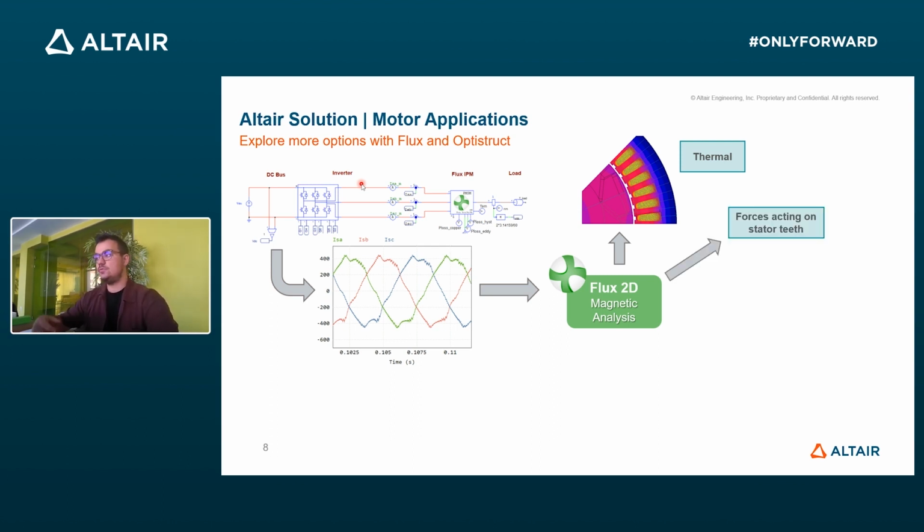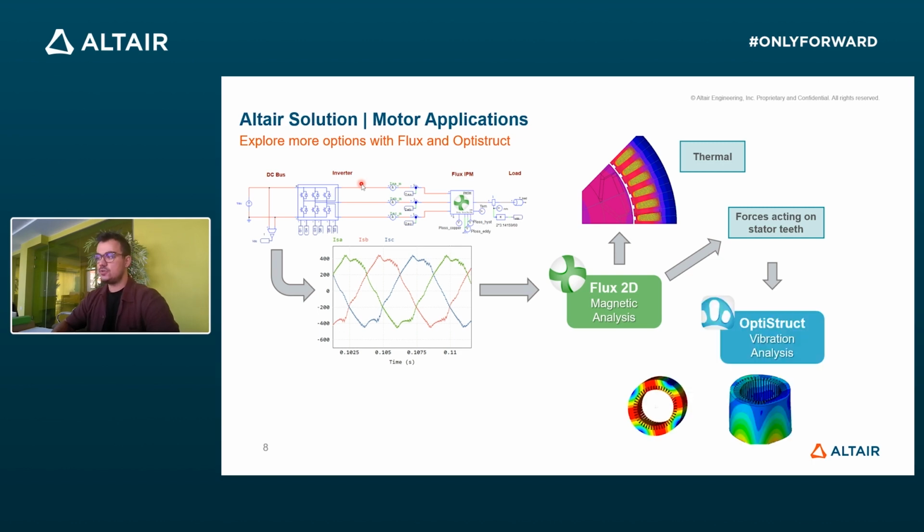And what is more, you can do some extra calculations to calculate the forces acting on the stator teeth. And based on those, you can run vibration and noise analysis to see how the harmonic content can affect the actual noise vibration of the motor.